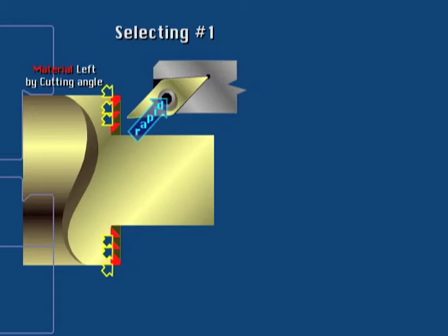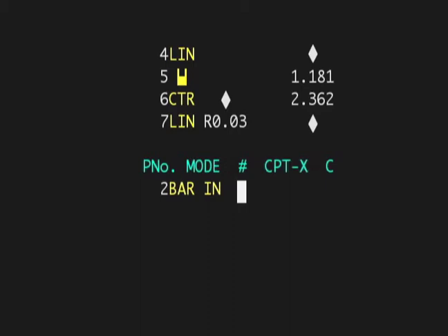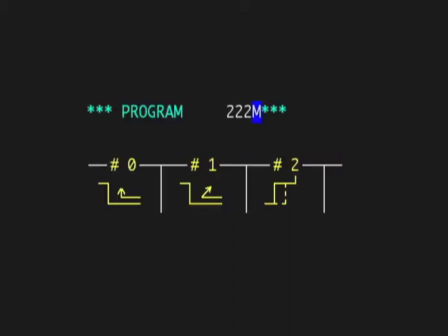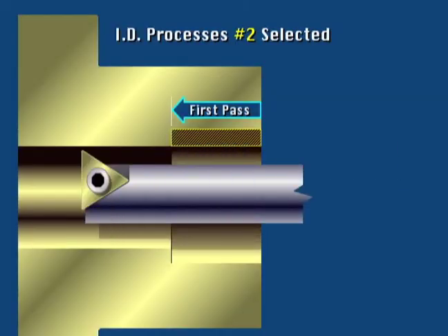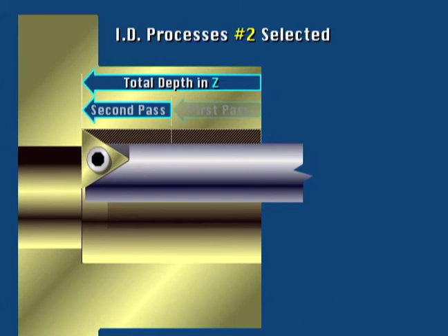This creates a somewhat faster machining sequence for the rough pass, since the slower vertical movement by the tool at the feed rate is not performed. If an in mode was selected in the previous machining part selection, the number 2 value would be available on the menu. This selection will cause 2 machining passes in the ID to create the depth of the feature required.